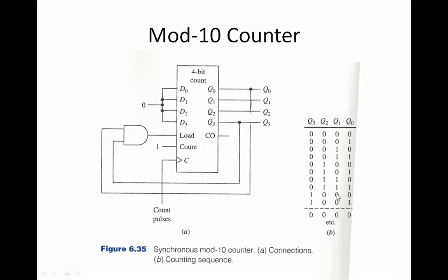So accordingly, I can connect this full thing to an OR gate. So if I am getting an 8, then directly I can connect that to load. In that way also we can design. Or for example, if I want it to stop at 7, so Q2, Q1, Q0, all these three I can connect and give to an AND gate. So the AND gate's output will be connected to load. Load is connected to 0. So after 7, immediately it will give me 0. So wherever ones are there, those you should connect to the AND gate. Understood?